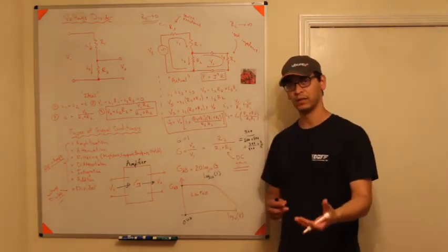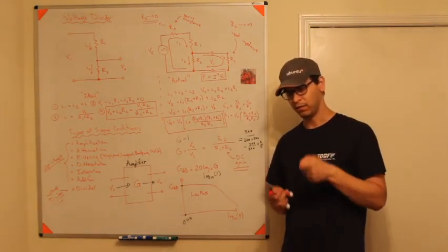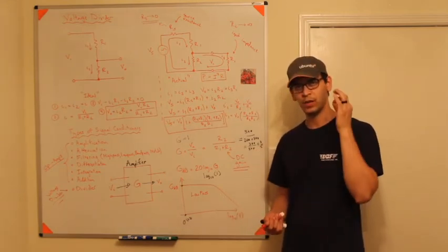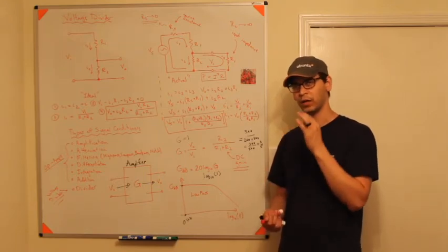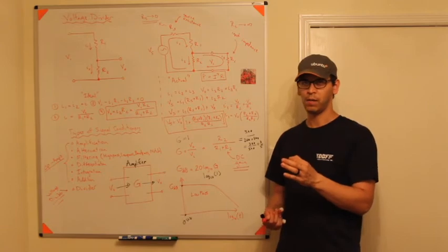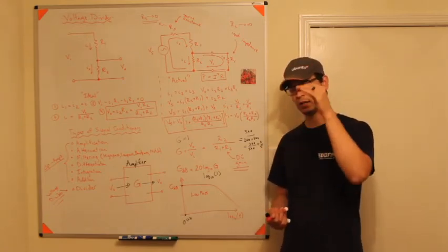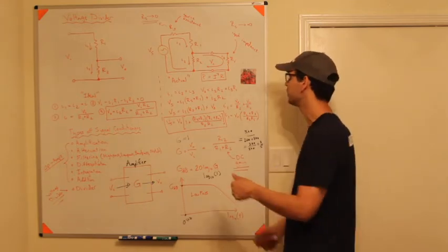And power is energy in a way. If I have a voltmeter hooked up to a system to measure the voltage, I want the least amount of power taken from the system. So I want the current to be as small as possible. And in order to do that, because voltage is equal to current times resistance, the only way I can drop current down and power down at the same time is to jack up the resistance.